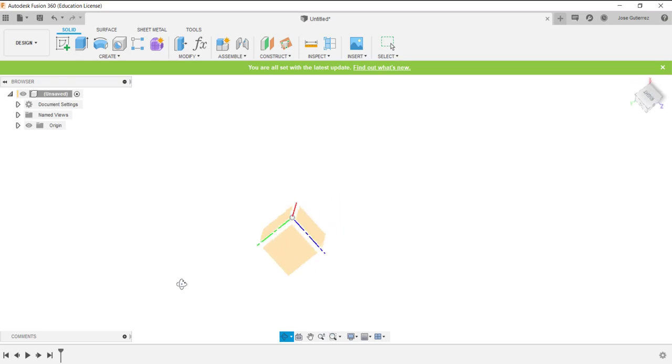Now, you don't have to use these. You could just navigate fully with the home icon, but I like navigating with my middle mouse and zooming in and out. And I apologize, it's actually for pan, if you want to move around, that's Control and the middle mouse. Here I'm dragging my origin across by hitting Control and clicking the middle mouse. So that lets you pan. You can also do that by clicking down here on the bottom toolbar. If you click Pan, that gives you this little hand, and now if you just click your left mouse, you can drag the model around.